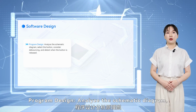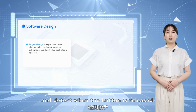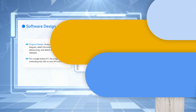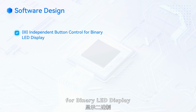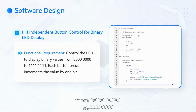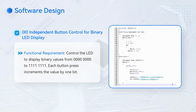Program design. Analyze the schematic diagram, select the button, consider debouncing, and detect when the button is released. For instance, for a single button K1, the program is as follows. 3. Independent button control for binary LED display. Functional requirement. Control the LED to display binary values from 0000 0000 to 1111 1111. Each button press increments the value by 1.